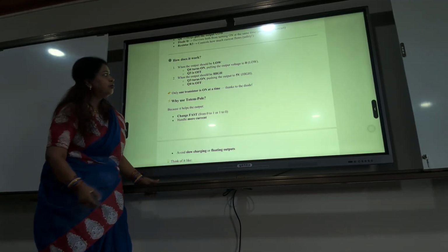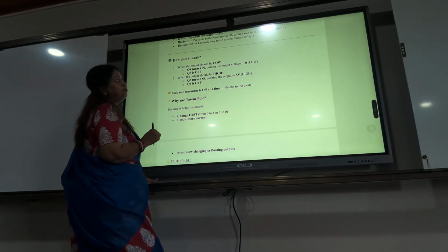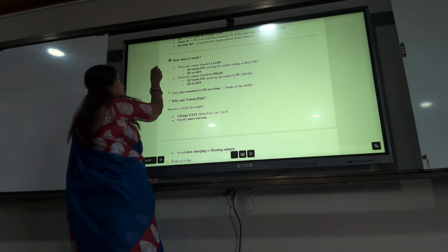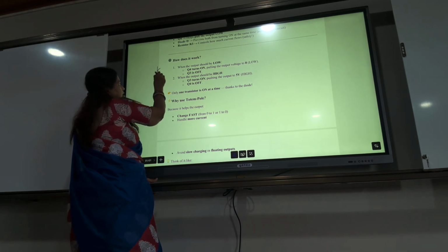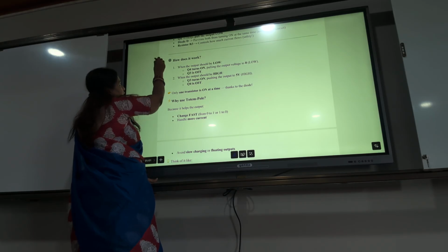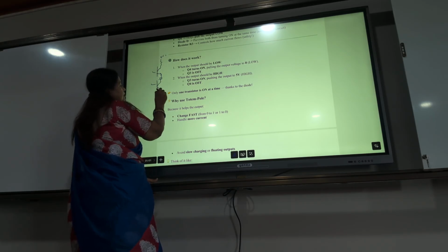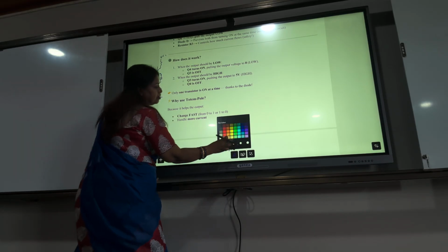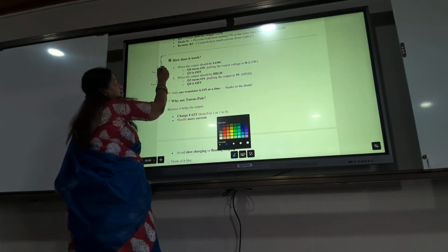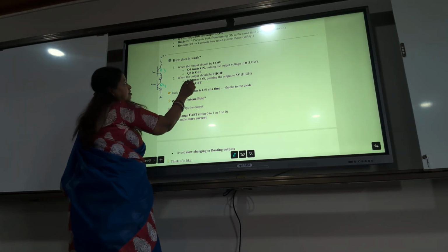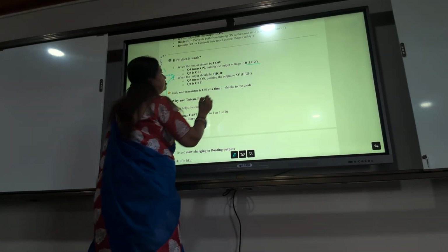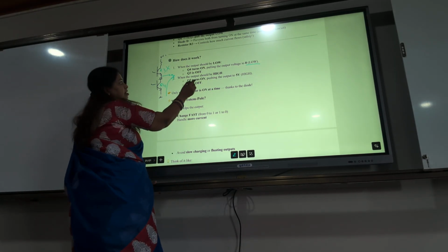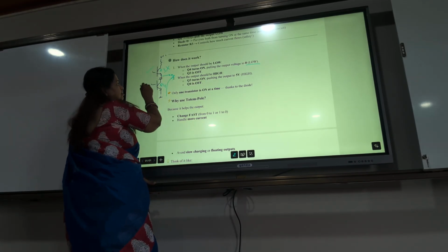So when the output should be low, Q4 turns on, bringing the output voltage to 0. So here you have two transistors, a diode, and a resistor. This is Q3, this is Q4. Q4 turns on, and this is connected to the load. Q3 is off.